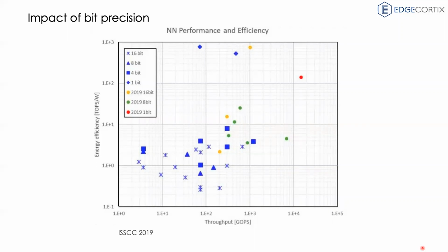By reducing the precision, you have less requirements of memory because you have effectively compressed the space, but typically you're also sacrificing some amount of accuracy. And what you can see here already is that if you compare the throughput requirements, so in the edge side, as we have already discussed, you would want to have high throughput, and at the same time, you want high energy efficiency. And being within around 8 bits of precision, you can really achieve very high combination of throughput and energy efficiency.